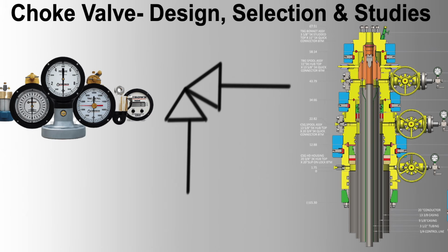2. Pneumatic choke valves. Example: commonly used in offshore platforms where remote control and quick adjustments are necessary. Advantages: fast response, quick adjustment capabilities for changing operational conditions. Remote control: can be operated from a distance, enhancing safety and convenience.